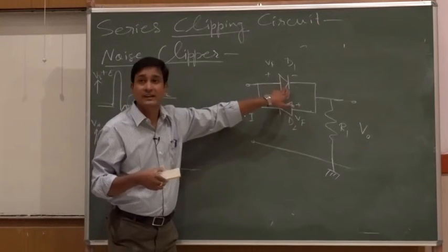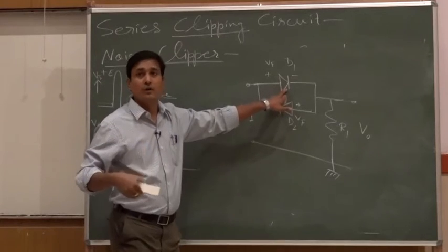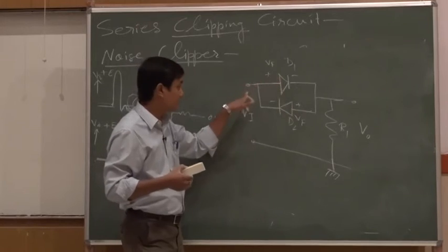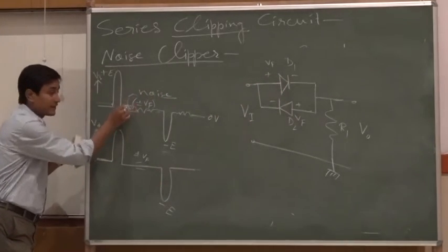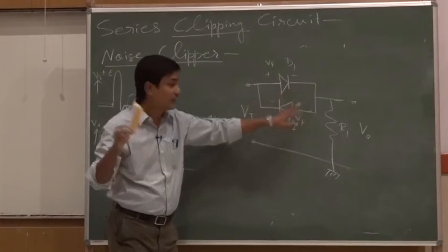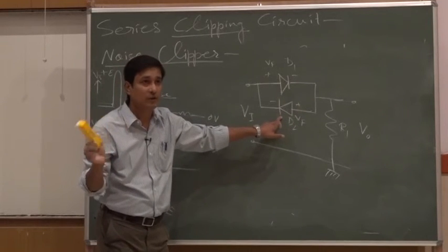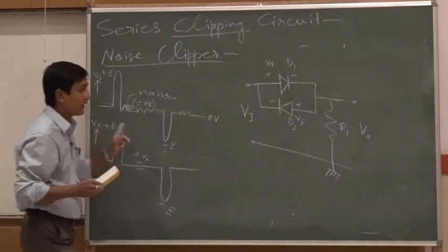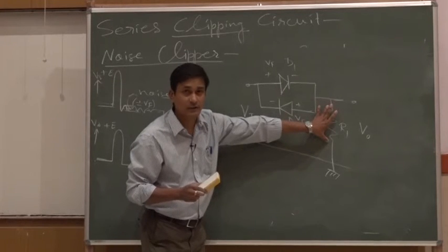It will be forward biased, or in a condition to give you current, only if the voltage you apply here goes beyond plus Vf. After you apply plus Vf, this is in conducting mode, and nothing to think about the other side, which is already in reverse bias. So no current will flow through it. For this part current will be flowing and finally voltage will be found across the R1.